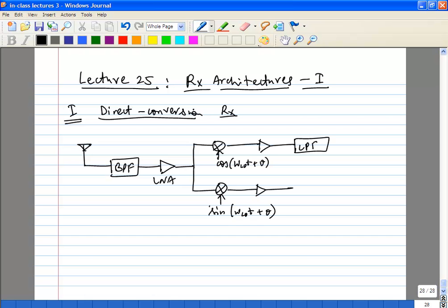Yes. Last class you mentioned that the in-phase and quadrature voltage components will be generated by the baseband. How are they generated? How is the baseband isolated to give the voltage components? You can get it from the amplitude and the phase of the signal. If you know the amplitude and the phase, A cos phi of t and A sin phi of t will give you that. Yes, definitely.